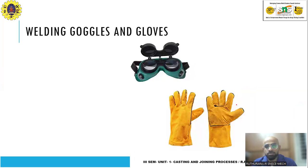And the safety equipment: welding goggles and gloves. Goggles are required to prevent the eyes from getting exposed to ultraviolet rays which are generated during the welding process. It's a very hot, luminant process, so a high amount of heat and light will be generated. If your eye is constantly exposed to this heat and light, then our eye may get damaged. So we are using goggles and gloves for safety because, as you saw, the temperature generated is 3300 degrees Celsius. It's a very, very high temperature. So safety suit and safety goggles should be worn all the time.